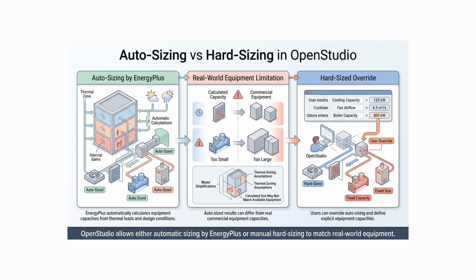Now, this explanation is intentionally simplified. In reality, EnergyPlus uses very detailed and sophisticated sizing routines that can handle many different HVAC configurations and system types. Still, the key concept to remember is this: even though you may not manually assign capacities to your HVAC equipment, every component in the simulation ultimately receives a specific size. Those sizes are calculated automatically by EnergyPlus based on zone loads, internal gains, and extreme weather conditions.